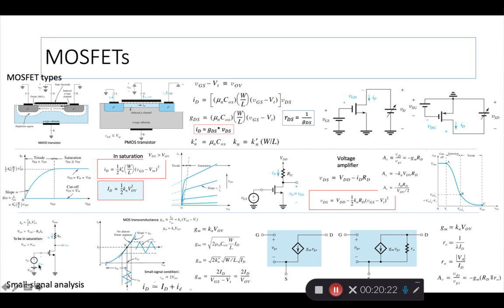So in the small signal model, which by now I hope you're familiar with, we have the drain, the biasing voltage and the signal voltage shown separately in series, and as long as the signal is small signal condition, meaning the VGS, the signal, is much less than twice the overdrive voltage, then we say we are in small signal, and then you can use the linear form of the output equation.